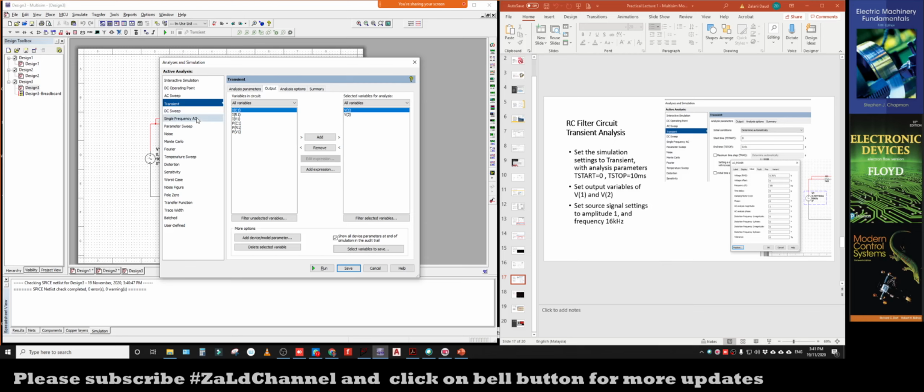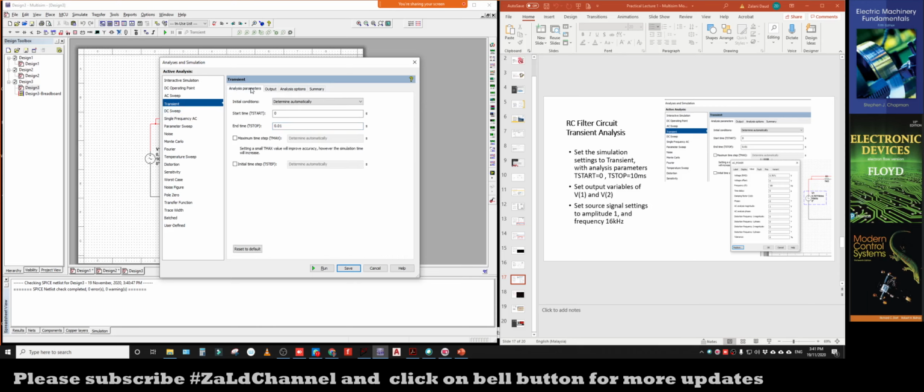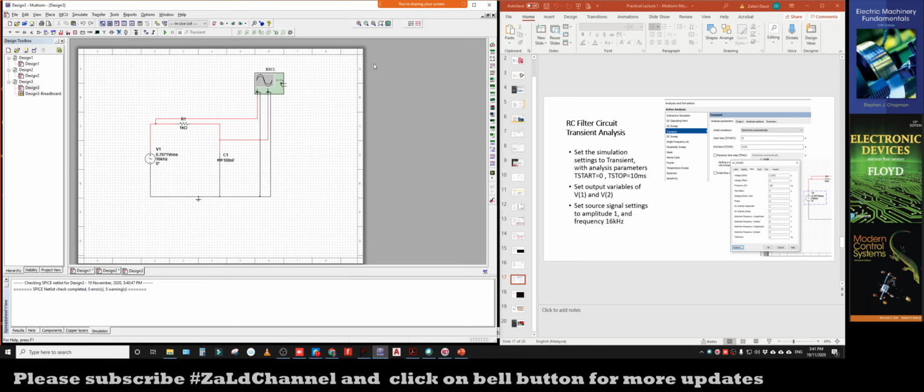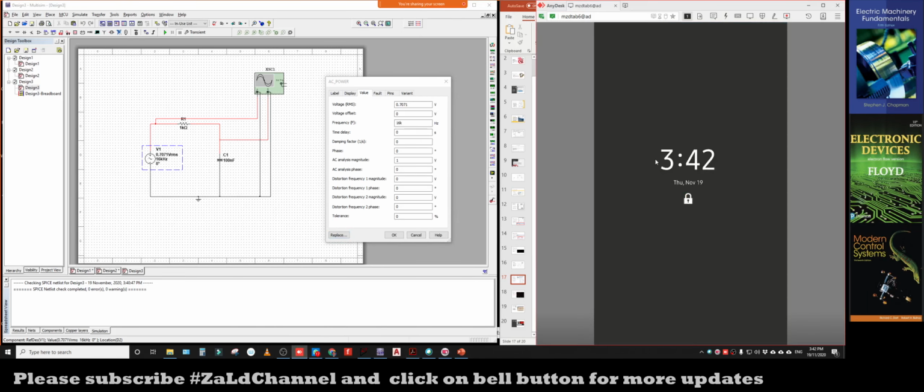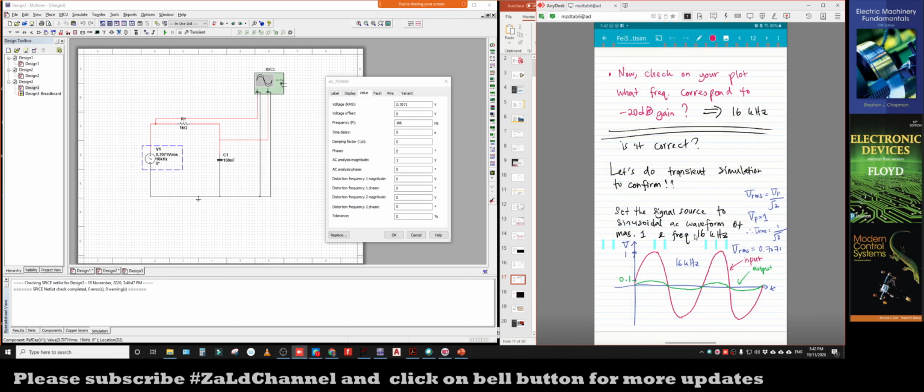There is not much change in the simulation settings. Basically, we just change the T start and T stop, which are 0 and 0.01. Since we would like to do the transient simulation, we want to confirm whether 16 kilohertz is correct or not. So what do we specify for this source? Let's say I want to change the input signal, as you can see in the handwritten lecture notes here. I have made some explanation here.